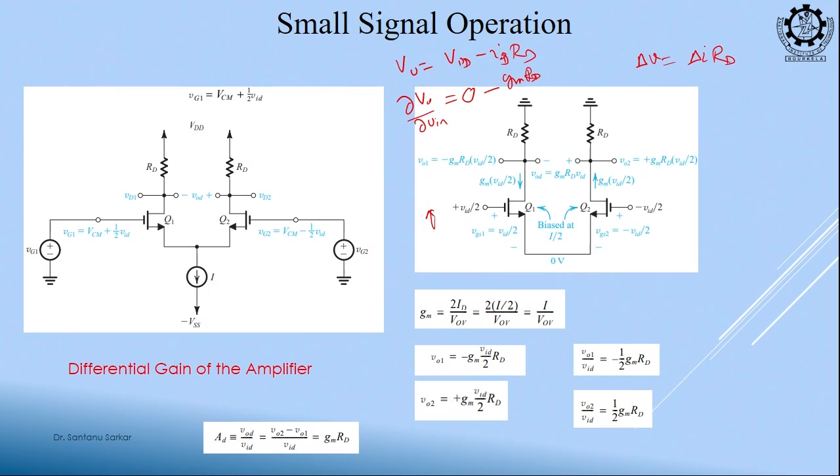agree. Have you seen this equation before? Which circuit? Common source. So, does it look like the common source? Yes, na. I am taking output from the drain terminal, source is common. So, this is like a common source amplifier. If we replace this current source with a resistance, and separate these two branches, this will be a source degenerated common source amplifier, agree.